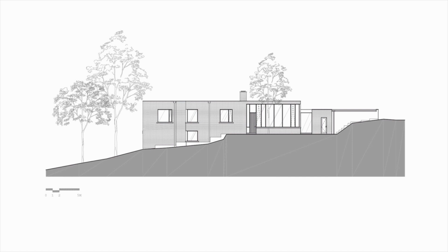Another example here of the elevation. Thickest line is the piece that we cut through. In this case, it's the terrain. Our next thickest line is the outline around the building. Then we get a little bit thinner. I think there could be a little bit more line weights in the windows. I think those could be a little bit thinner. They're a little thick in this particular drawing, and I think that would help it read. The bricks themselves are very nicely rendered in a nice thin line weight.